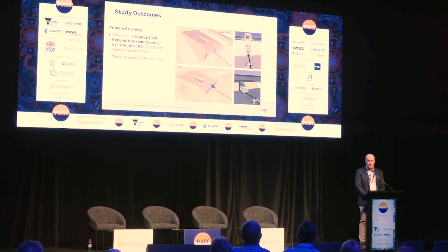But the real benefits there for us in terms of your owner is that your installation cost and your associated capex with that piece of equipment is significantly reduced because your earthworks is dramatically reduced over what a primary gyratory crusher would need to be. It really is very much in a sweet spot between the performance parameters of a jaw crusher, but at the scale of a gyratory crusher. So we are very, very excited by this. This was baked into the study, and there were some significant cost savings that we achieved with that.